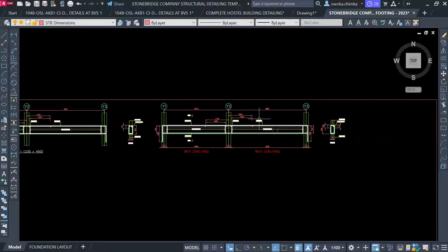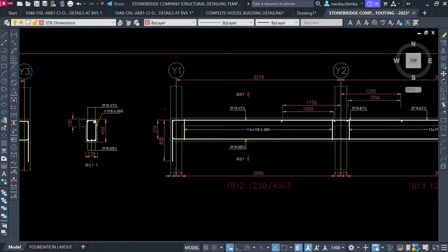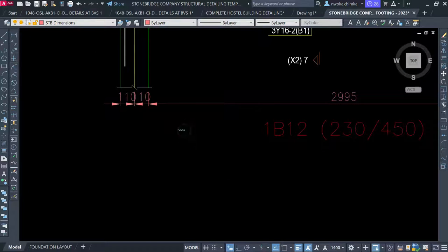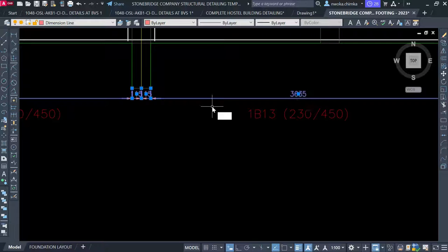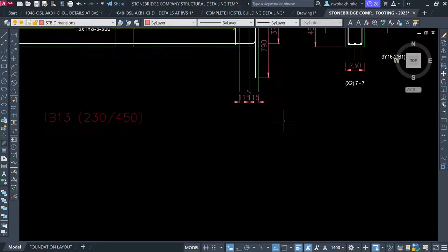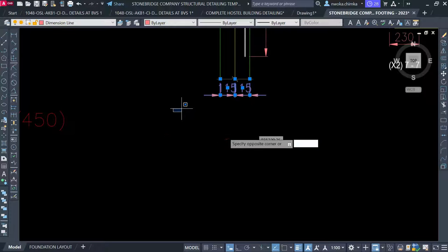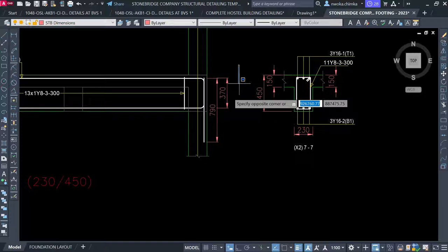After, I'll show you how to place this on the back sheet, which is on the template for printing. So I'll remove other things which are not needed here. These dimensions are not necessary. I'm just removing this one, not all of them. So if you have this on your own, remove that. I'll remove this also, enter, and remove this one also, enter, and remove this one here also, enter.